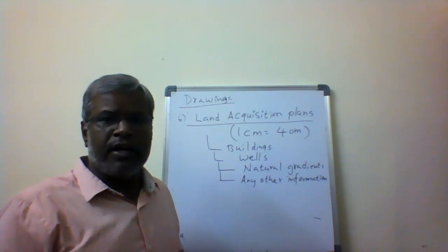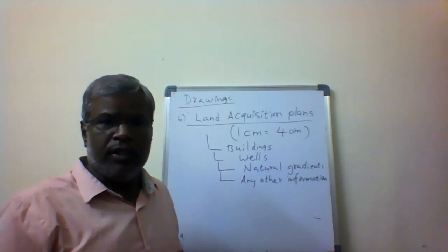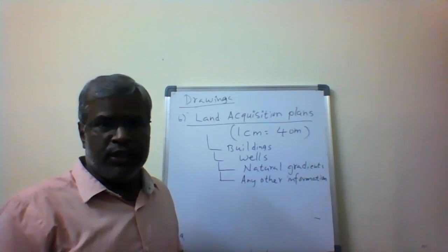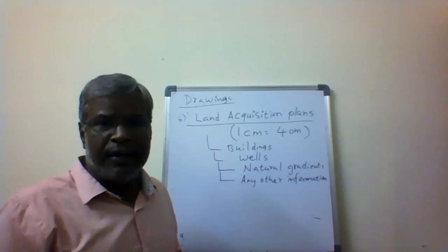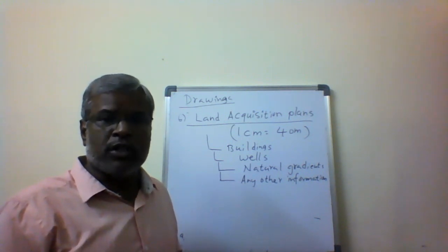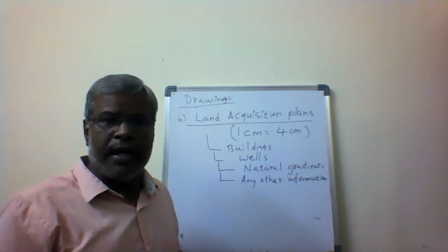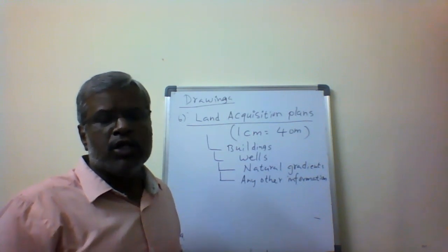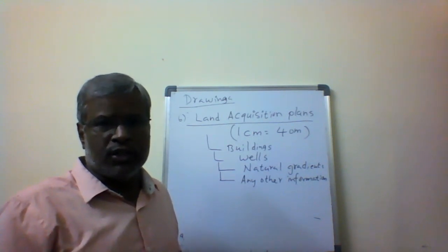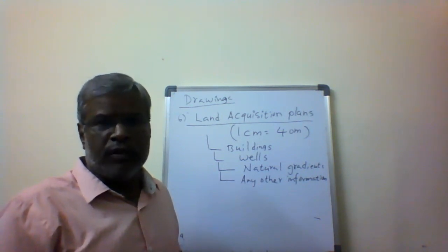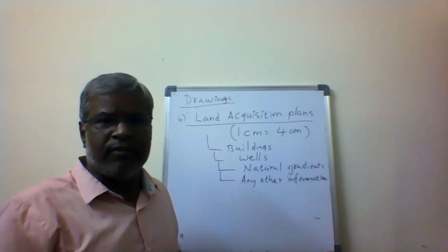So that's why land is acquired in advance, such that we can extend the road in the future as well, and there is no need to give compensation. If we do not acquire the land for the future 10 years now itself, and then want to go for any extension later, what is going to happen? We have to demolish the adjoining constructions and give compensation for that, so a lot of money will be incurred. For that purpose, we prepare the land acquisition plans.